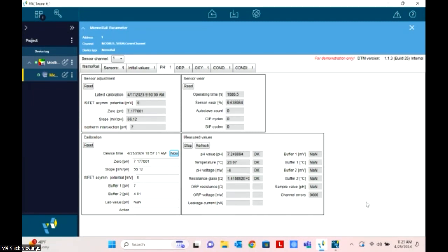So what you see here on the screen share, I've got a live view. I'm connected to this Modbus DIN rail mounted transmitter. Now I'm bringing it into the framework Pactware, but imagine, if you will, that this is your control system. Or even if you're an integrator or a skid builder, and this is your local HMI where you have all your instrumentation on your skid coming into, we're just simply pulling these Modbus registers continuously.